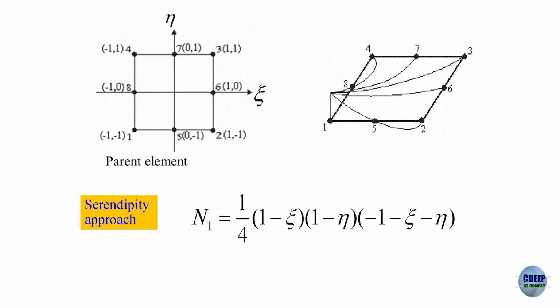And I am not interested in writing down C0, C1, C2 like that, finding out, substituting, rearranging, no. Now we have left that part. So now we are going to see if I can use the characteristics that we discussed in the previous class and reviewed in today's class. Can I find out what would be N1, for example? By looking at the system, can I write? What should be N1? N1 should be 1 at node 1 and should be 0 everywhere.